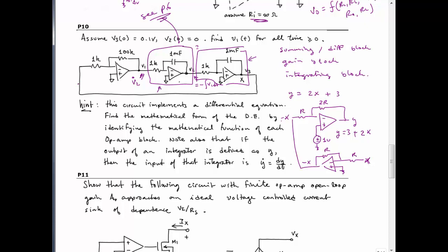Basically, since it's a closed loop, you're going to be able to write an equality of the form, like in a differential equation, you might come up with something like x dot plus 3x is equal to 0. That's what you're going to end up with here. And you're going to write it in terms of either V3 or V1. And it looks like, because you have 2 integrators, that you might have something more than just a first derivative term in your expression.